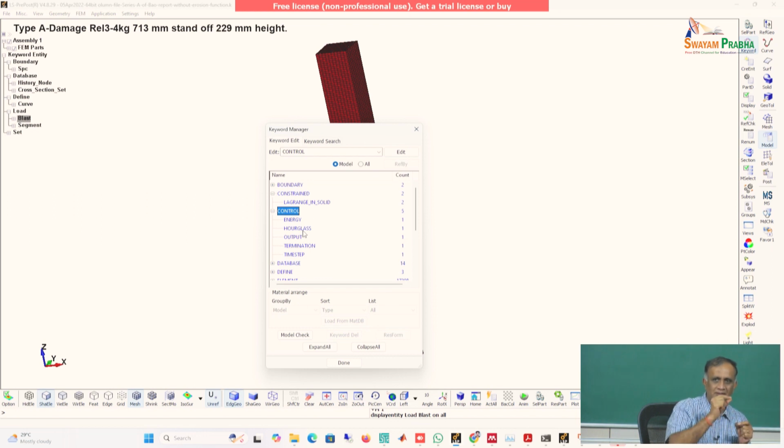When you do time stepping, you don't want to go 4 points, you want to reduce it, but then hourglassing can occur. It changes shape, but the whole property itself has not changed. Artificially, it does. So you have to have an hourglass type.